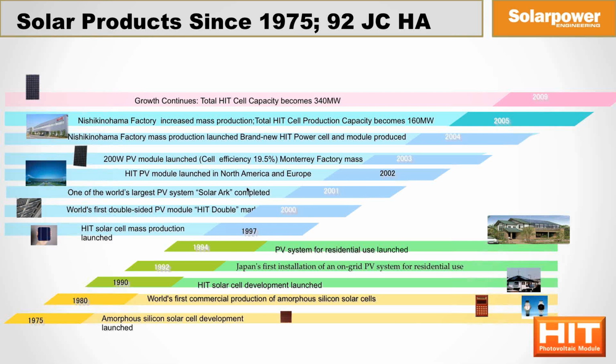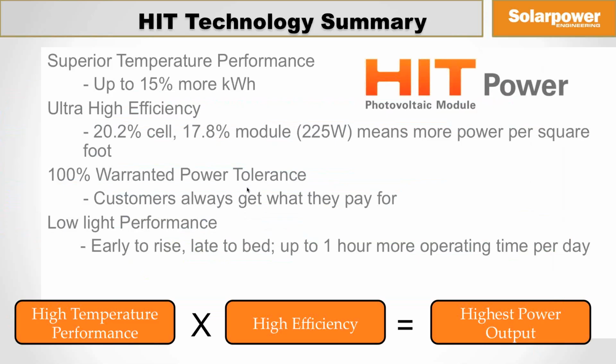These are some characteristics of what's on our panel. It's a 225-watt panel. Other crystallines will go up to as many as 400 watts. Not so long ago, a 150-watt panel was pretty common in the industry. And it raises the issue of how much effort and research money you want to put into increasing efficiency, and how much you want to put into the rest, the balance of system, the other costs that go into a module.